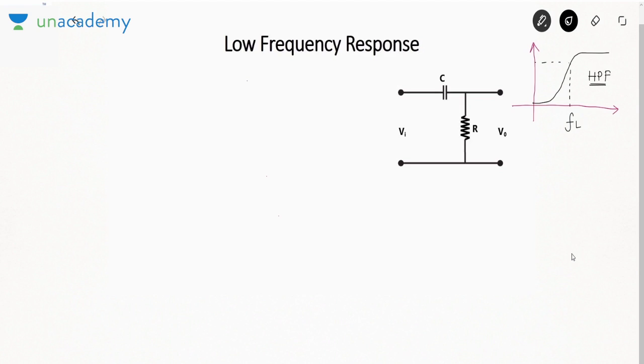I am not drawing the curve further. That is, I am not getting into high frequency range. I am talking about low frequency. So if you see only the low frequency curve, you will feel like it is a high pass filter. And that is why the circuit that I have given you, it is a passive, passive means no active device, first order high pass filter.